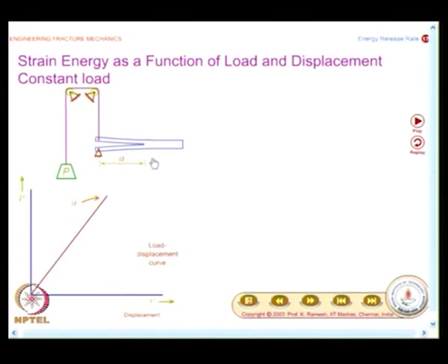What this sketch shows is you have a double cantilever beam specimen, you have a long crack, the crack length is given as A, and to make your visualization easier, it clearly shows through a cable system you are hanging a load P. So, it is very clear that you are having a constant load applied to the component.